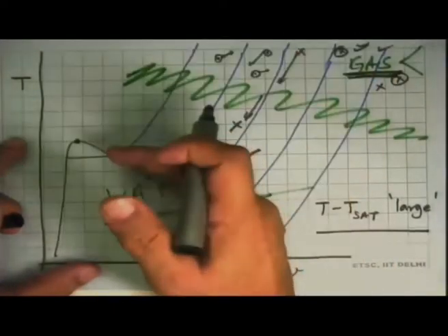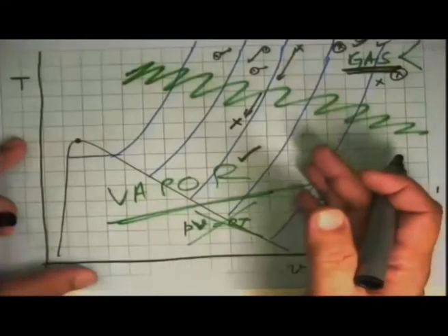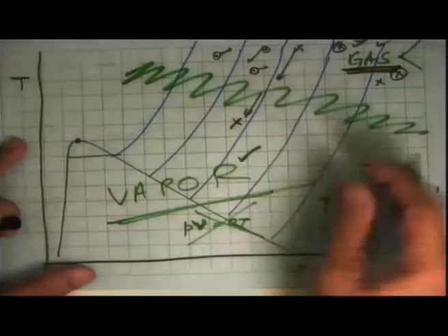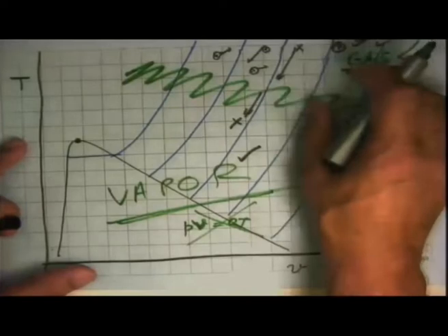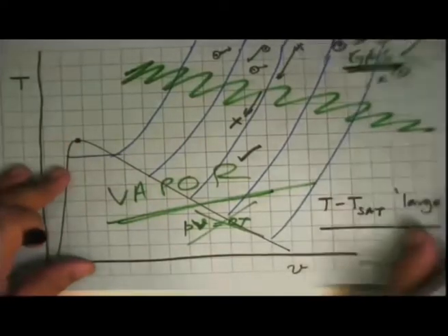This behavior begins to deviate sharply when we are in this region, and the moment we are in the saturated state and liquid state or the supercritical state, it completely breaks down. There will be some regions of the vapor behavior where we can still say that ideal gas is approximately valid, or at least apply a correction to the ideal gas equation of state.